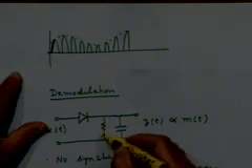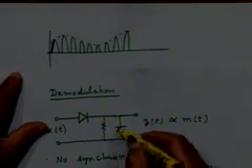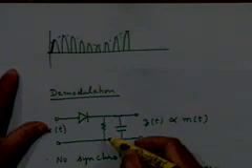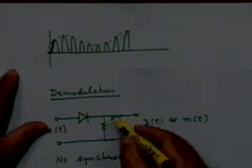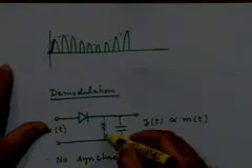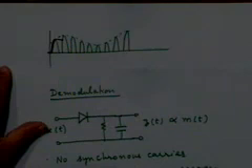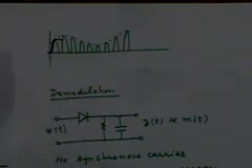However, due to the fact that there is a resistance here, there is a discharge phenomenon that will take place. So this voltage value starts to decrease a little bit depending on the time constant of the discharging, right? So let us say it discharges slowly, and this is the way it will discharge, right?